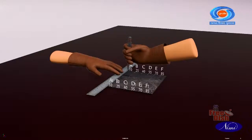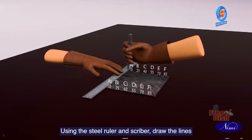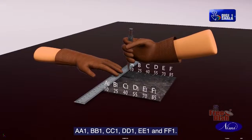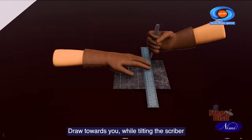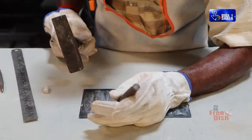F1. Using the steel ruler and scriber, draw the lines AA1, BB1, CC1, DD1, EE1 and FF1. Draw towards you while tilting the scriber in the direction of the stroke.